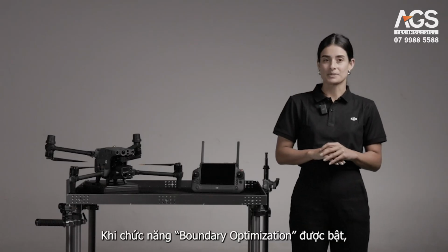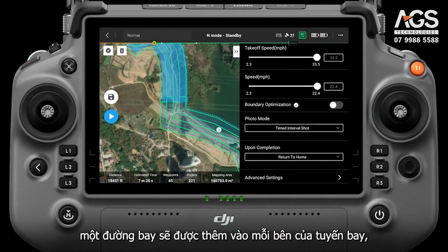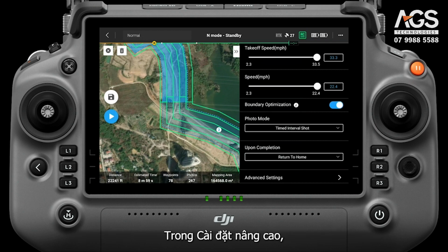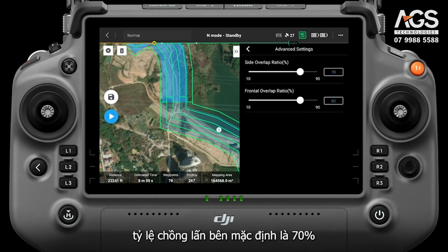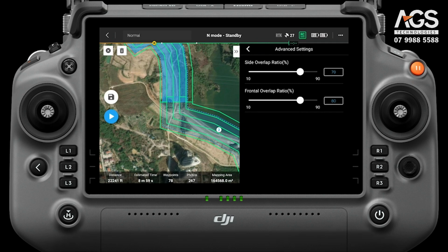Once the boundary optimization function is on, one flight route will be added from each side of the flight band, which means you get more photos of the band edge details. In advanced settings, the default side overlap ratio is 70% and the frontal overlap ratio is 80%, which is suitable for most application scenarios when shooting with a wide-angle camera.